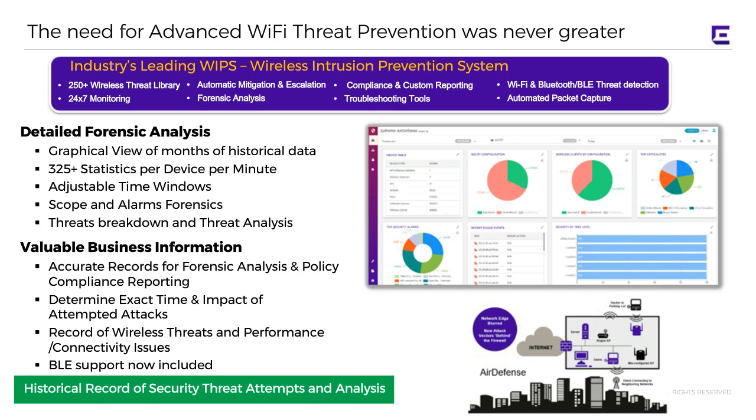Spectrum analysis is built in, and it provides us the ability to monitor and troubleshoot the airwaves for interference like microwaves or things like that. So basically, it's a complete spectrum analysis tool that can measure all the air frequency and interference. We also have the ability to provide historical data, so you can actually look back in time.